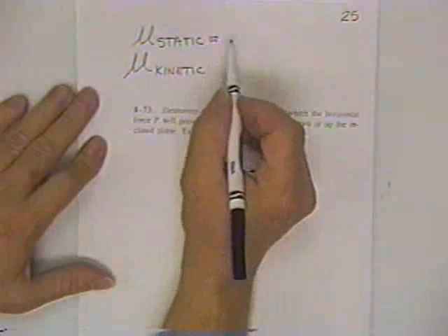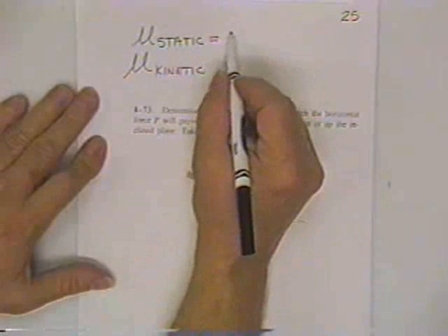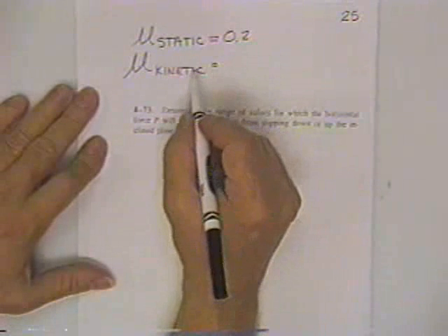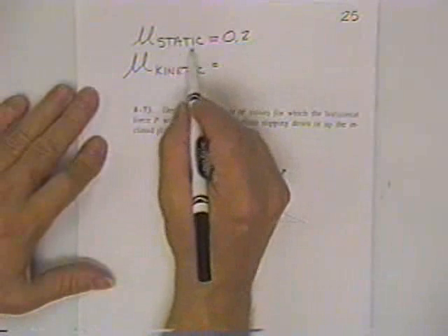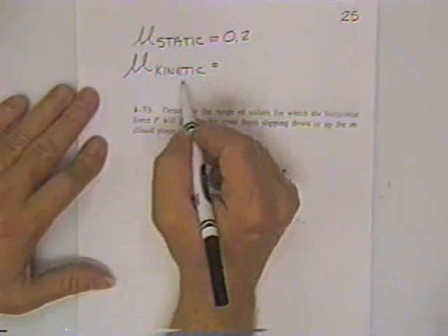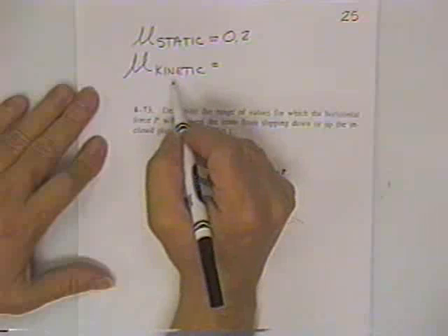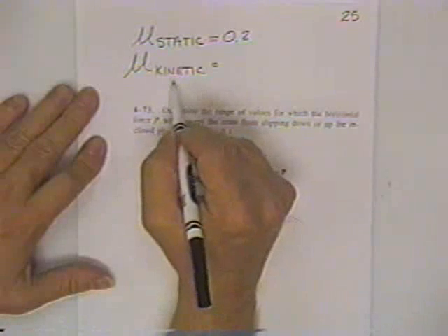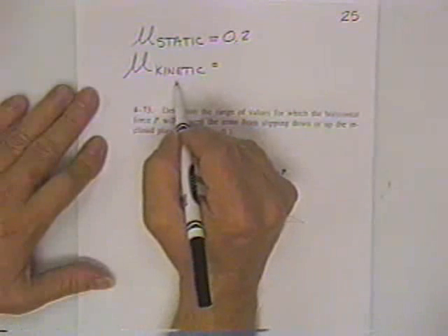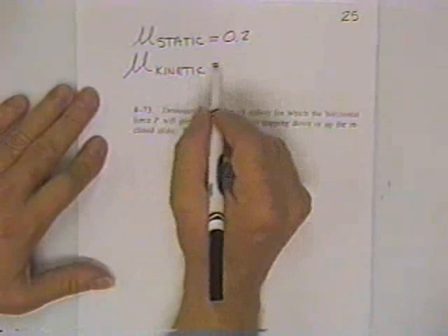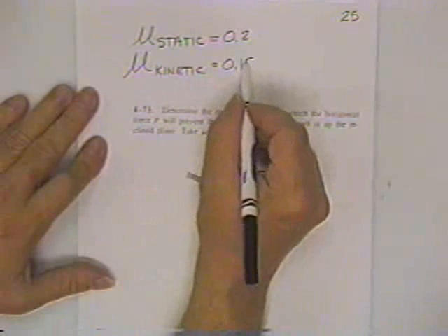The static coefficient of friction is generally larger, might be 0.2. If that's the case, then this is the coefficient of friction it takes to break it loose. Once you get it moving, the little raised spots and indentations and imperfections that used to be kind of locked together are pretty much dynamically rattling across each other, and so this number drops maybe to this.